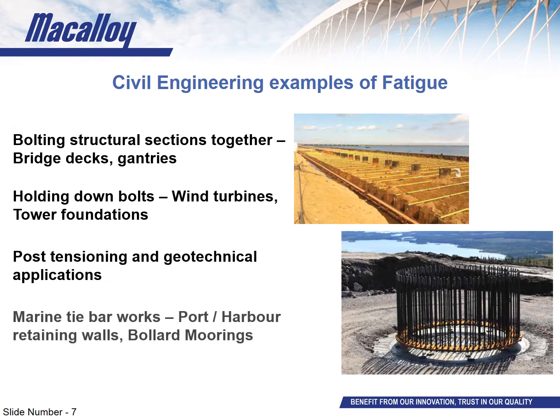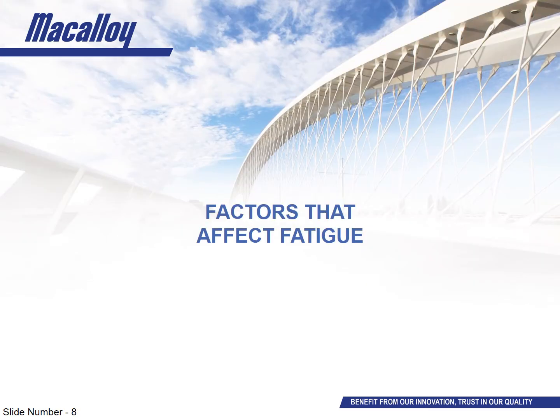Finally, applications in ports, such as marine tie bars that are buried under a mound of earth and shipping containers. Now, these can be subjected to fluctuating load and cannot be inspected, so appropriate fatigue allowance has to be put in place. Obviously, these are just examples, and each structure or application should be assessed based on its own conditions or requirements.